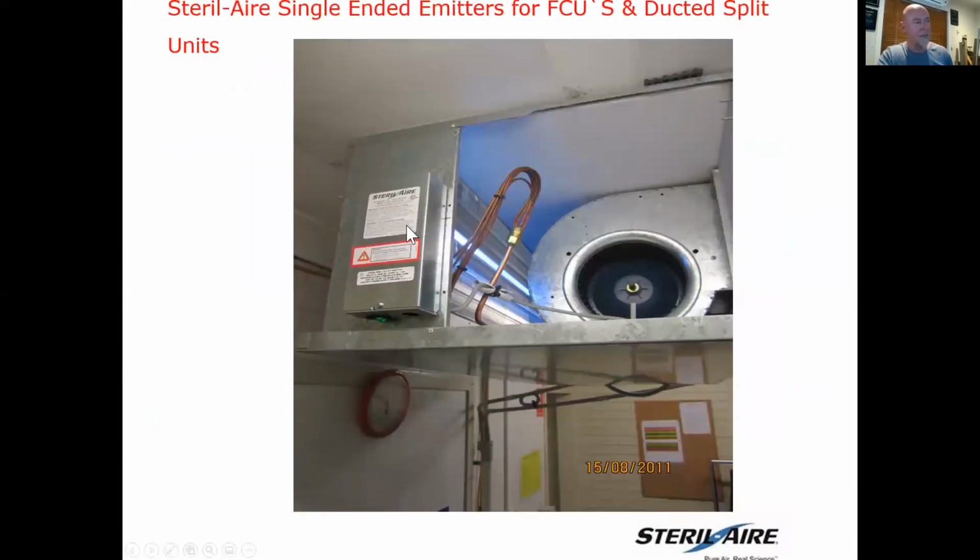This is an example of a fan coil unit with the RSE fixture installed. Basically, you drill one hole, 20mm hole, mount the fixture on the side, slip the lamp through, hook up the power, and it's done. It's a 15-minute installation. Very easy to do.